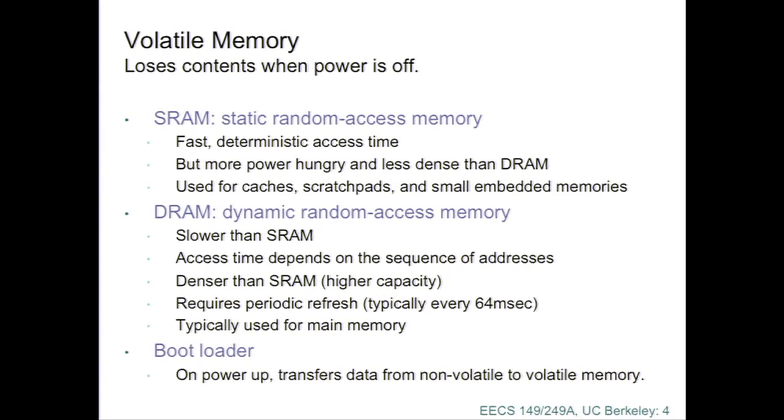So for practical reasons, that's rather difficult to do, which basically means that anytime you're accessing dynamic RAM, you don't know what the timing is going to be. And you're going to have to design your system for worst case, all right? Which means that no matter how good your memory is in terms of being designed for average case, for laptop use, you're going to have to design your embedded system for worst case as if it was a really crappy memory, okay? So that's kind of a problem. In a sense, the memory designs are not well suited for embedded system applications.